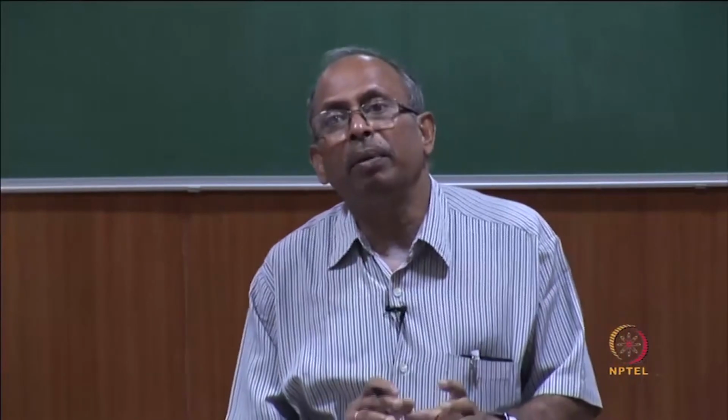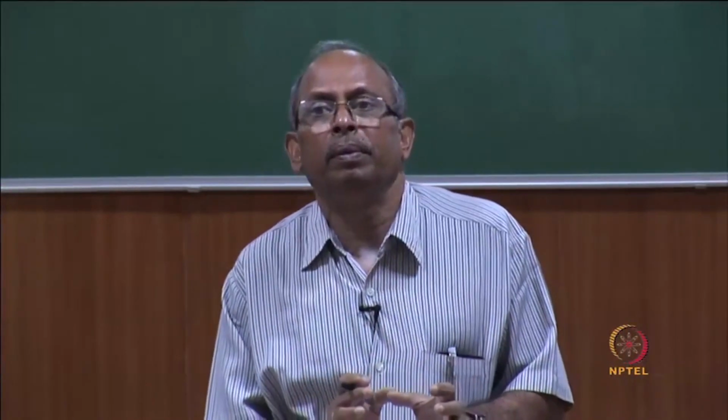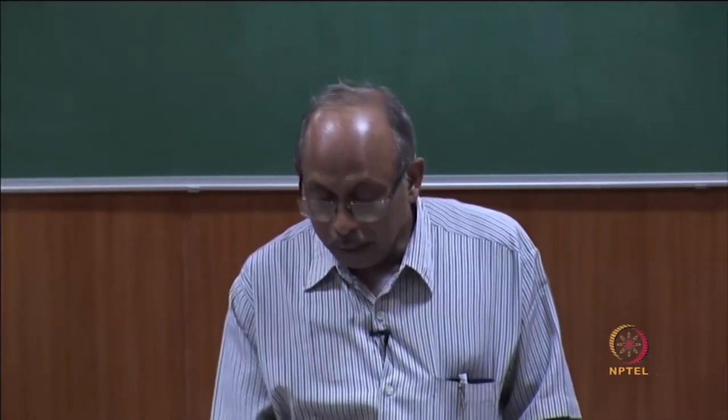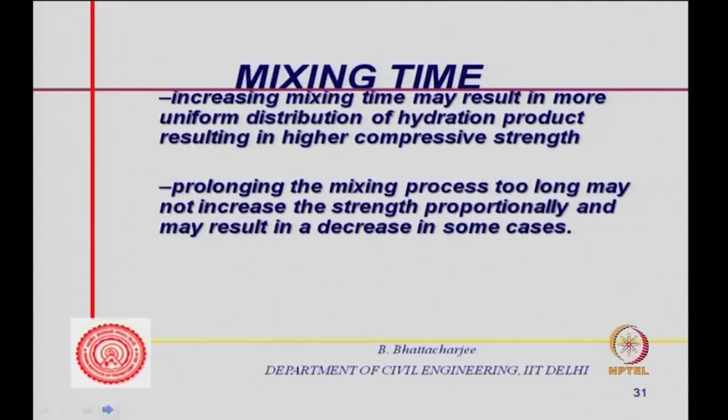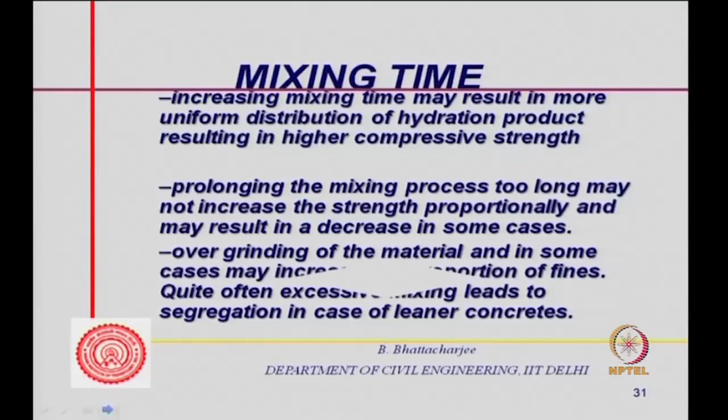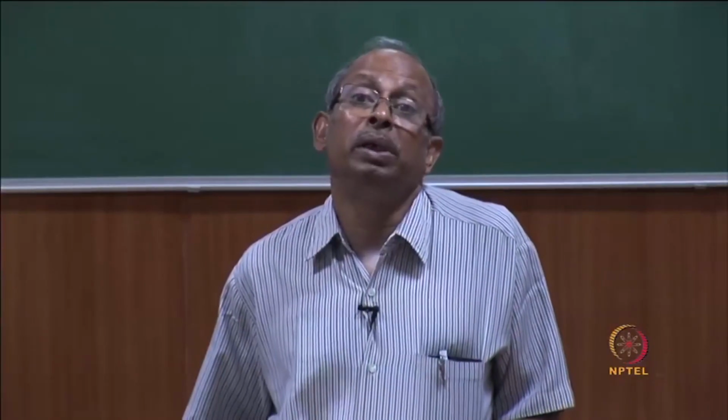So, it actually causes a better dispersion and more uniform scenario, and therefore, higher compressive strength. But there is a point of diminishing return. If you go on increasing this, it may not increase the strength proportionally, and sometimes it can even cause decrease. All right. So, there is a limit up to which you can do it, because mixing may cause overgrinding of the material, too much abrasion between aggregates, and in some cases may increase the proportion of fines if the aggregates are weak.